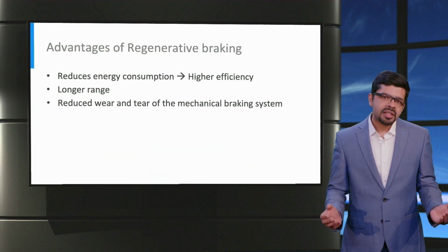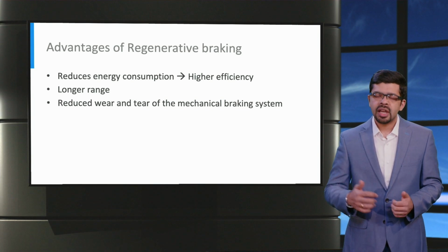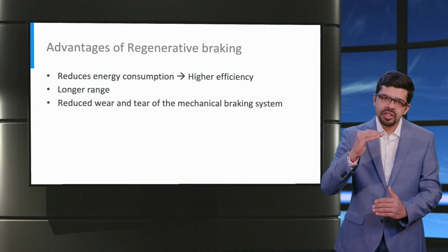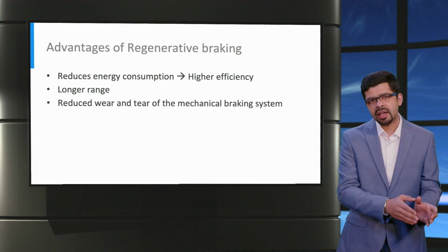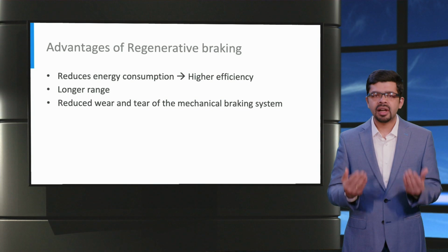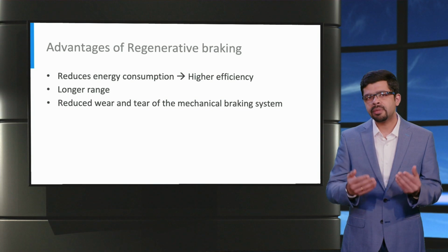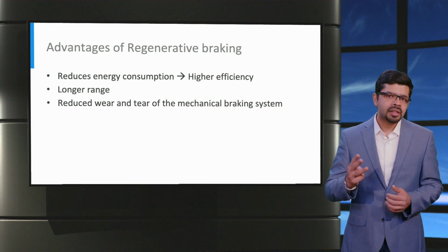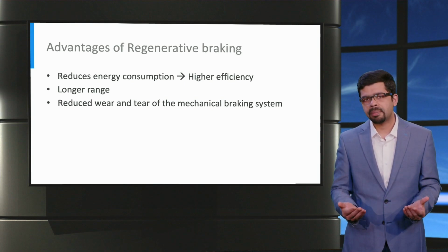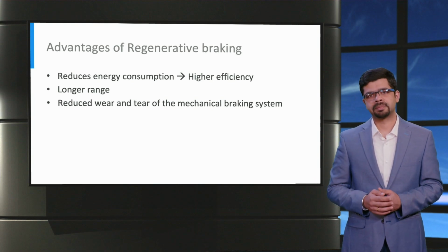The key advantages of regenerative braking are threefold. First, regenerative braking reduces the energy consumption and therefore increases the efficiency of the vehicle, as part of the kinetic energy can be recovered and used later. Second, an electric car with a higher efficiency leads to a longer range of the car for a given battery size. Third, regenerative braking reduces the wear and tear of the mechanical brake pads or brake shoes, resulting in a longer lifetime of the mechanical brakes.